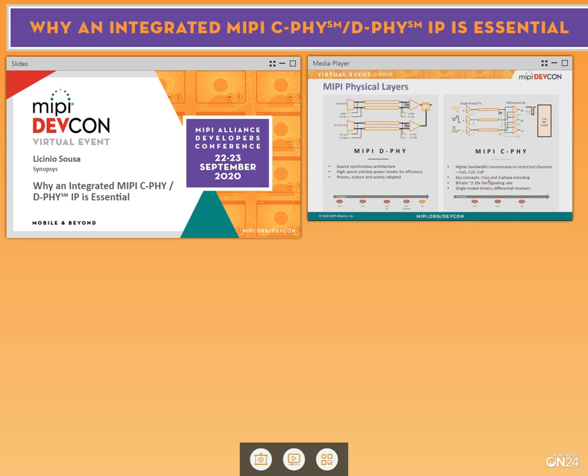If you look at the diagram, you'll see that the transmitter looks like a single-ended driver, a single-ended transmitter, and the receivers are differential, which is unique. But everything works fine because of the rules in terms of encoding and mapping that make sure that everything works in concert. These three wires work in concert. There is no contention. There's always 100% transition density that is guaranteed, which kind of helps with the receiver implementation.